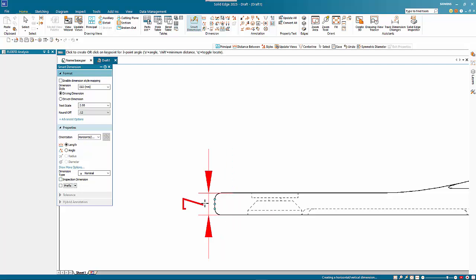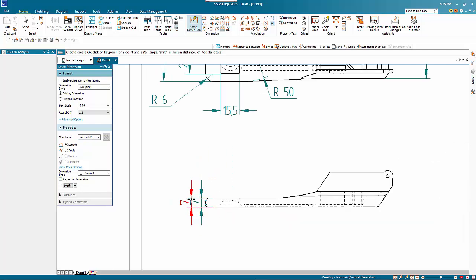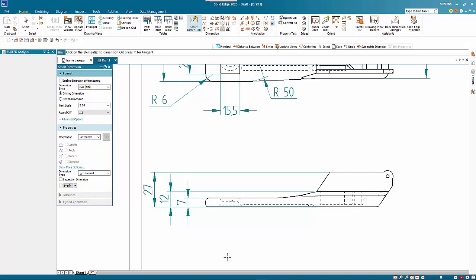Again, coming back to key points doesn't always work nicely. So we've got 7 mil on there. We can go from here to this line here and place that one in. And again, I could have done this with a distance between dimension, that will give me all off the one datum, so it's sort of less input.